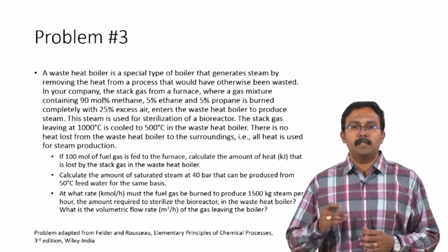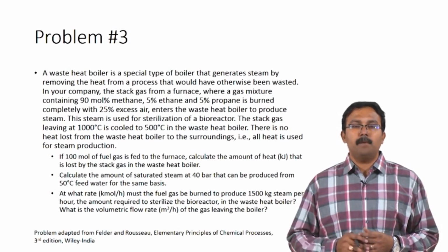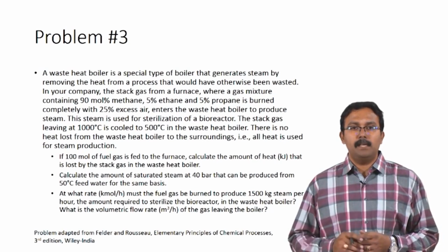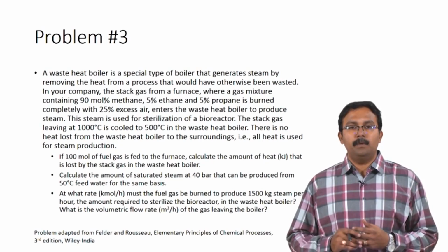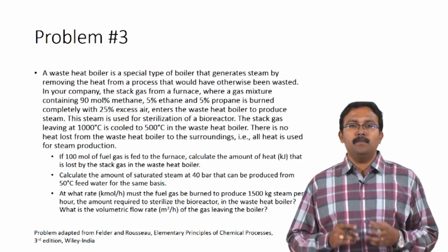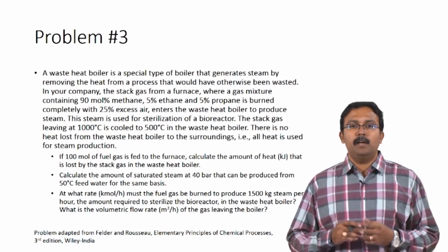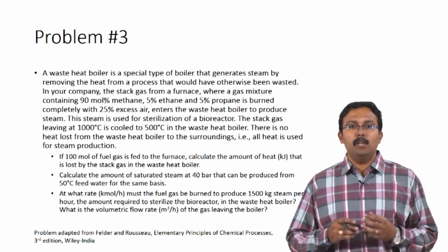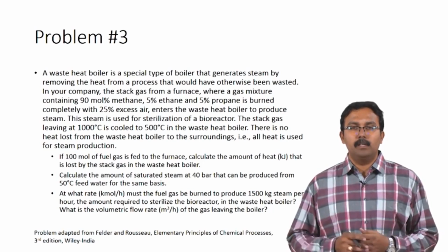Calculate the amount of saturated steam at 40 bar that can be produced from 50 degrees Celsius feed water for the same basis. At what rate in kilomoles per hour must the fuel gas be burned to produce 1500 kilograms of steam per hour, the amount required to sterilize a bioreactor in the waste heat boiler? What is the volumetric flow rate in meter cube per hour of the gas leaving the boiler?